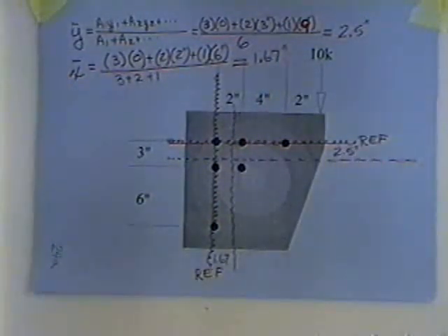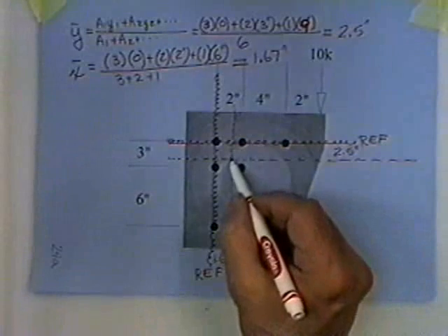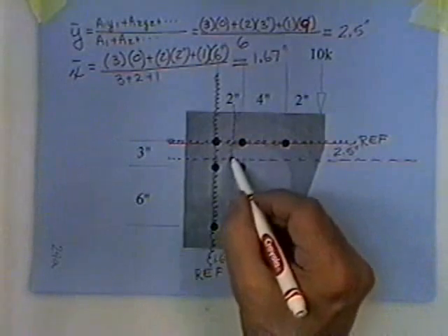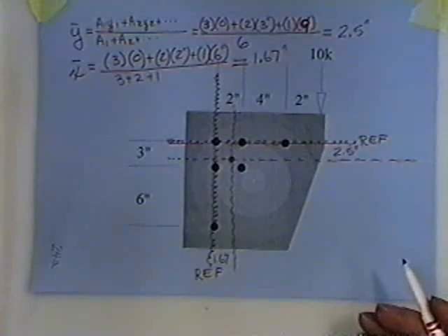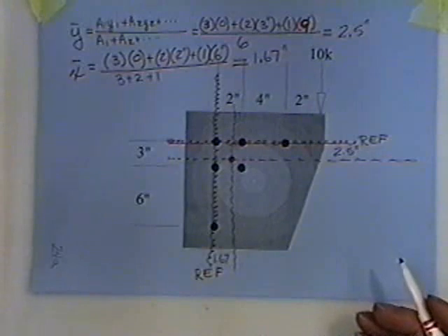Now then, bolts have a moment of inertia, incidentally, all these calculations are on page 24. We have a moment of inertia due to the bolts. The bolts are too tiny to have a moment of inertia about their own centroid, so we throw out their I0 terms. And all that's left, because they're so tiny, is their A D squared contributions.